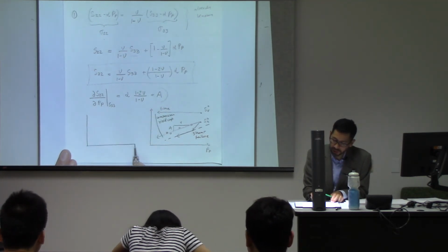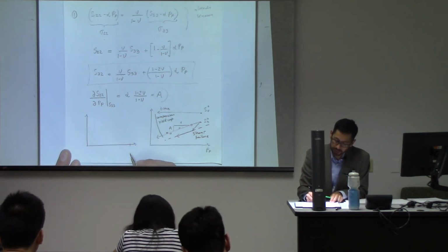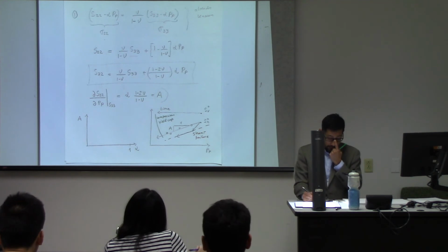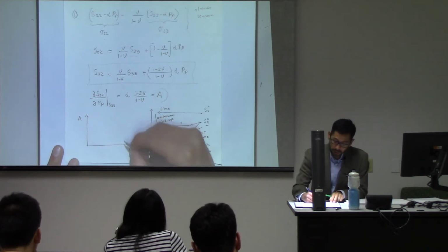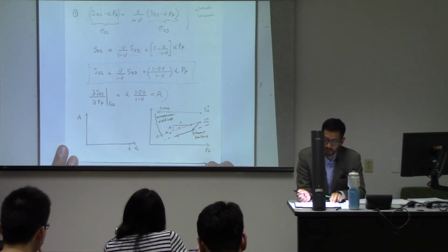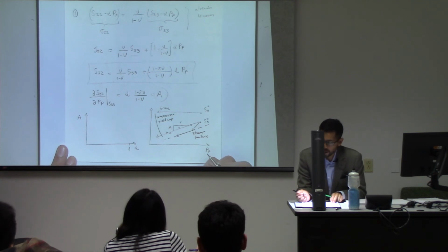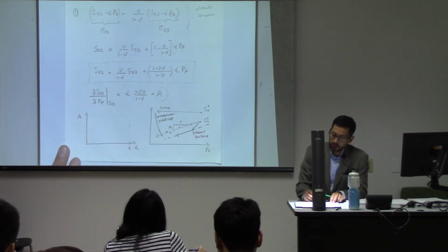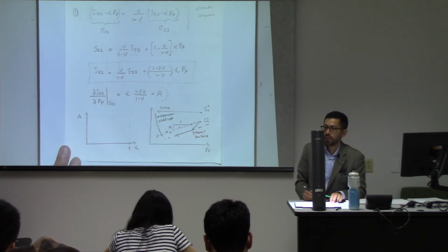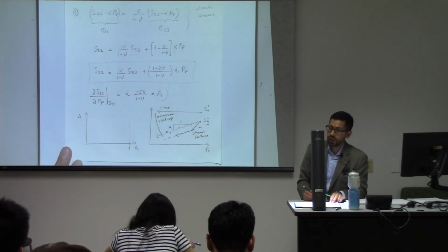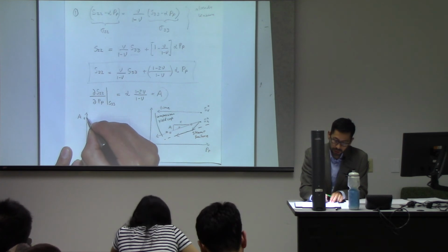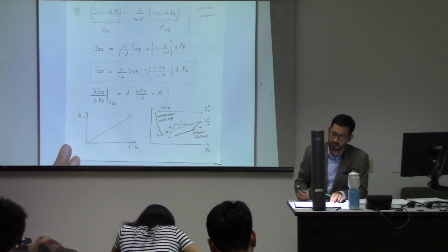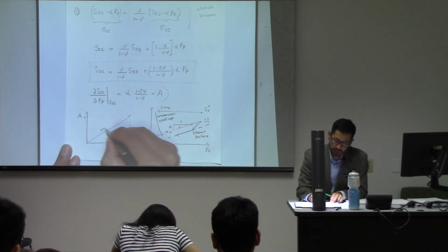So you see that we have two variables over there. One is the Biot coefficient, and its maximum value is equal to 1. And the other one is going to be the Poisson ratio. What if the Poisson ratio is equal to 0? What is going to be the coefficient A? Let's assume that the Biot coefficient is equal to 1. So if the Biot coefficient is equal to 1 and the Poisson ratio is equal to 0, the coefficient A is going to be 1. And everything in between is just going to be proportional to the Biot coefficient, so it's going to be a linear relationship.